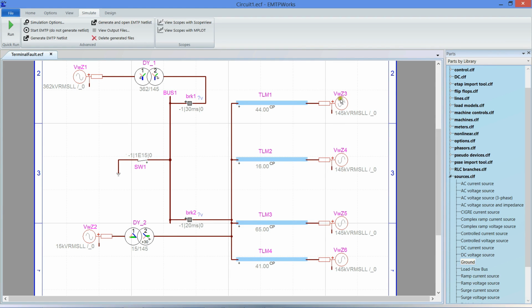But here it doesn't really matter, especially because the frequencies following the TRV are way faster than the power frequency. But again, in a study, it's better to initialize them with their power constraints. Okay, so let's run the simulation.